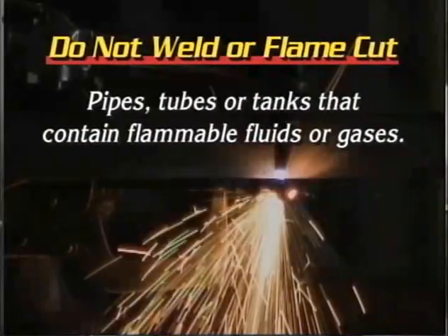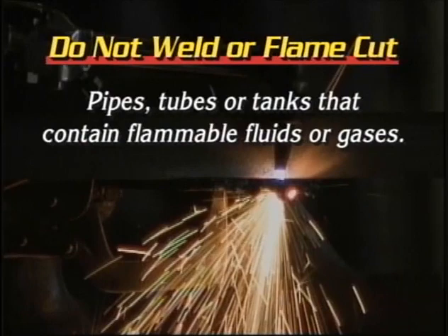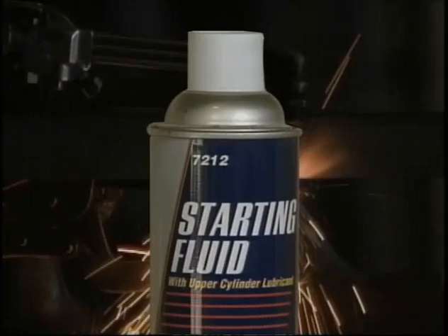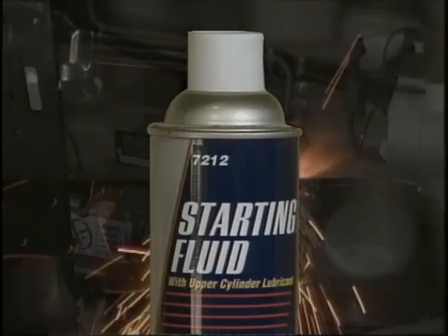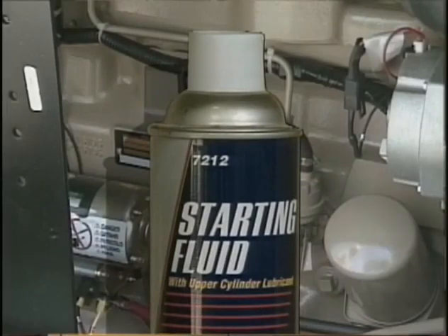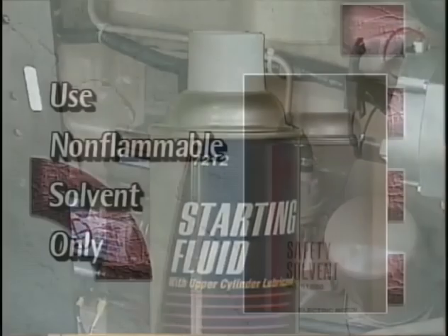Do not weld or flame cut on pipes, tubes, or tanks that contain flammable fluids or gases. Ether is flammable. Do not smoke when using ether. Always follow the instructions on the ether can and in the manufacturer's manual for your air compressor.